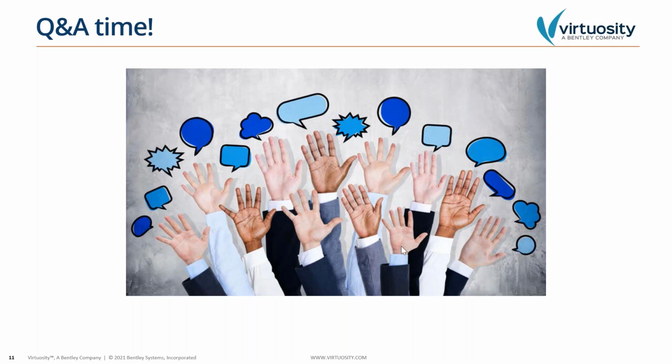In the applied connection, can we release a member in modeling? Yes, RAM Structural System has the member release commands, same as STAAD.Pro. But most of the time we don't need to do that because the ability to model the gravity and lateral members automatically takes care of the majority of the releases. The gravity members will have moment release applied to the ends of those members, whereas the lateral members don't have those releases. In addition to that, we can also manually assign those releases.